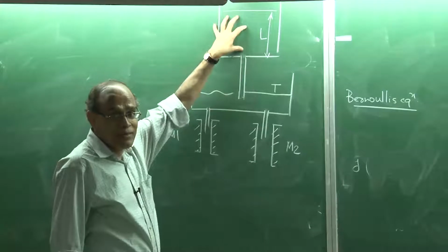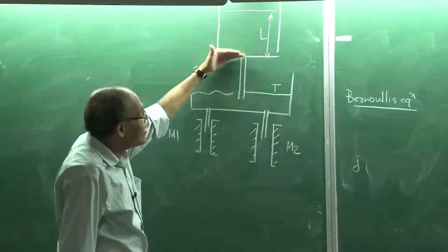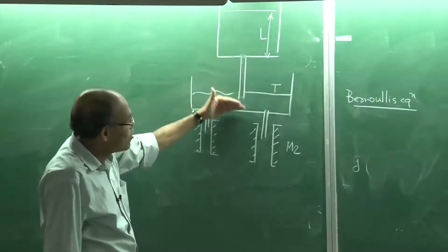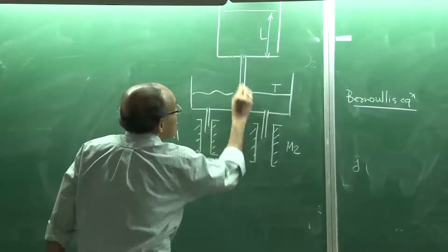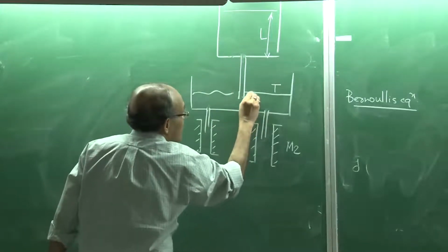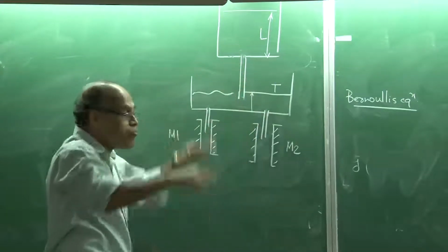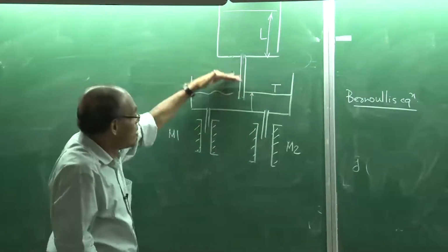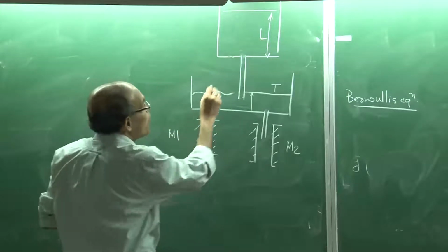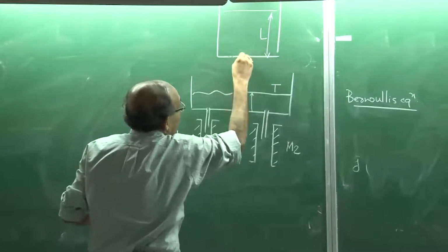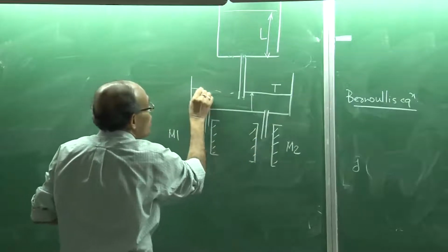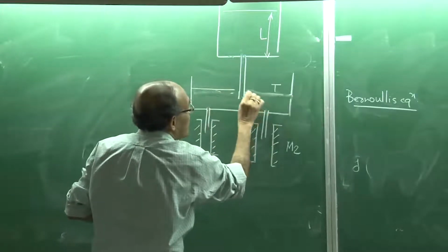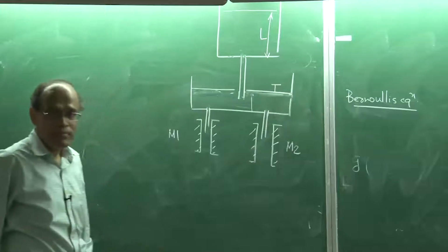So, from the ladle, therefore, the flow rate really changes into the tundish. Now, in the tundish, if the flow rate fluctuates, then the tundish level can go up and down because of the flow rate coming in. So, whatever is the flow rate from here, we manage the same outflow rate, and as a result we maintain a constant depth in the tundish.